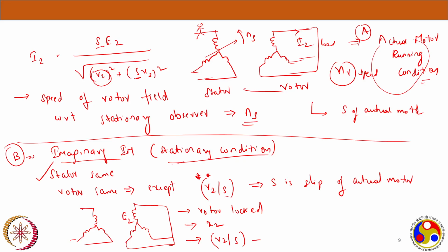E2, R2 by S and X2. Now what will be the frequency here in the rotor? Since S is equal to 1, my rotor frequency will be the same as the supply frequency.